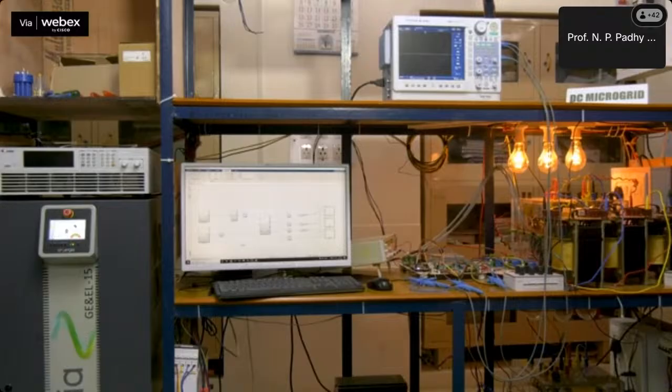Before enabling the control loop, the sequence of powering up the test bed is as follows. The first step is to turn on the power amplifier to apply the desired DC across the DC side of the IGBT stack. The second step is to turn the grid emulator on at the required grid voltage and close the PCC switch.